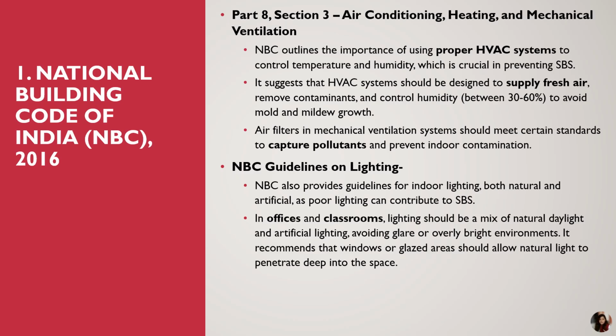NBC guidelines on lighting. Based on NBC, we have to provide certain lighting for indoors, both natural and artificial, as poor lighting can contribute to SBS. Offices and classrooms should use a design with more natural light, along with artificial light, like a fusion of artificial and natural light. Mostly the daylight factor should be used more, around 75% should be used completely in the morning hours with natural light only, so it avoids a bright environment, and you can use windows and glazed areas in order to have a good lighting system.